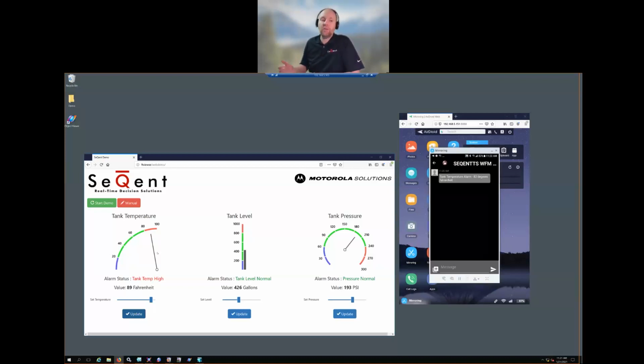Once again, escalation is entirely user configurable, so you can create as many different levels of escalation as you require. The last level of escalation is my phone call here. So hopefully you could hear that message coming through the telephone there. So again, just demonstrating the ability to go through that escalation when an alarm occurs based on an OPC trigger.